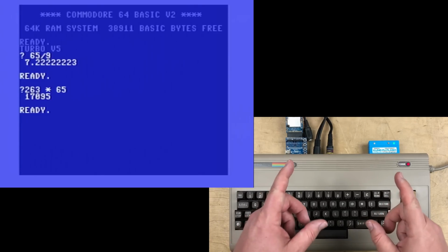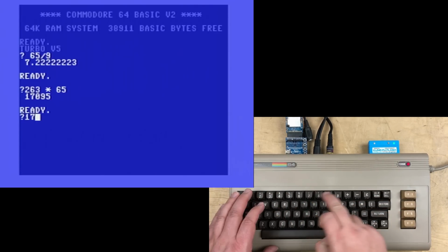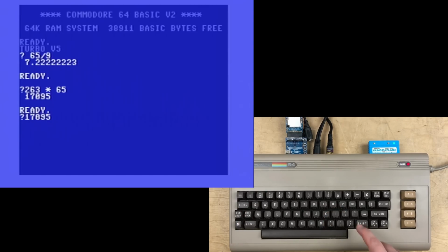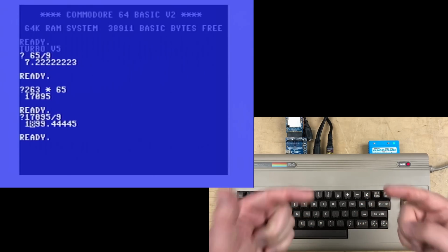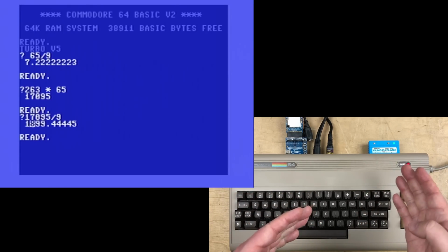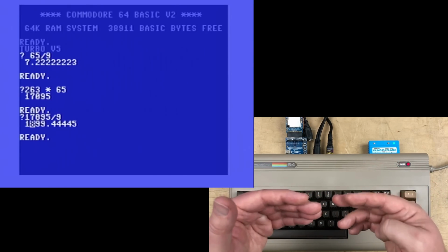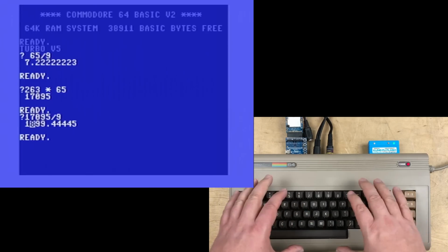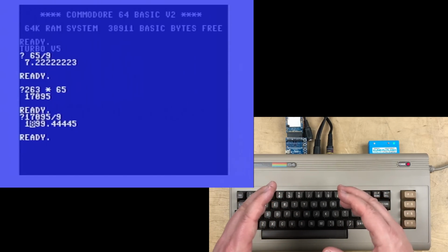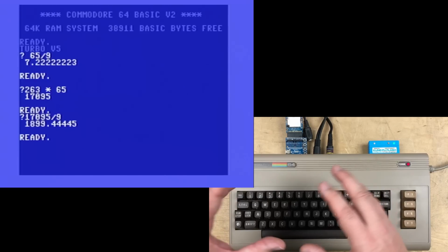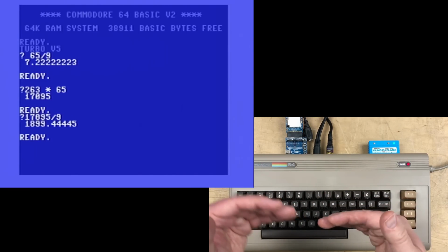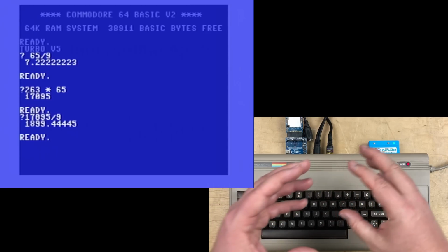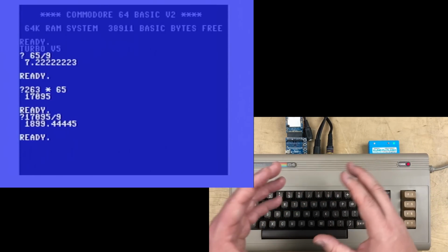1,795 machine cycles per frame. And if we try to divide that, say, by 9, it's not an exact number of border color changes per frame. Therefore, it's not going to look stable at all. Our code isn't syncing to the video display at all. So any animation or any effect that we see is kind of just coincidence. It has to do with the repeating pattern and how we pick up on patterns as they shift about.